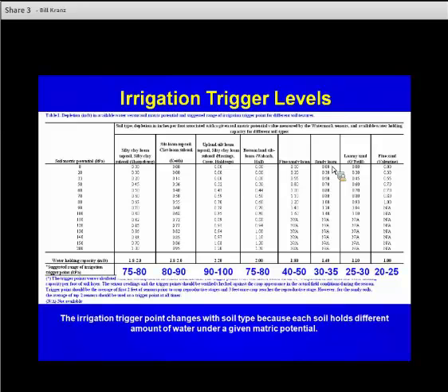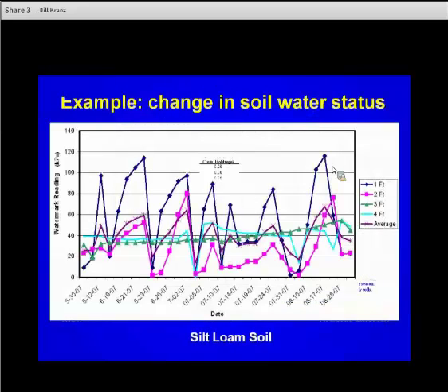Basically here we're talking about when we'd like to start irrigating or be irrigating when we have different readings from the soil water sensors, because what we're getting over here on the far left is a soil matrix potential, and we can convert to how much water has been removed from the soil profile in the table, but we want to utilize maybe a little different approach and use some trigger points as to when we want to make sure we're done irrigating out there in the field.